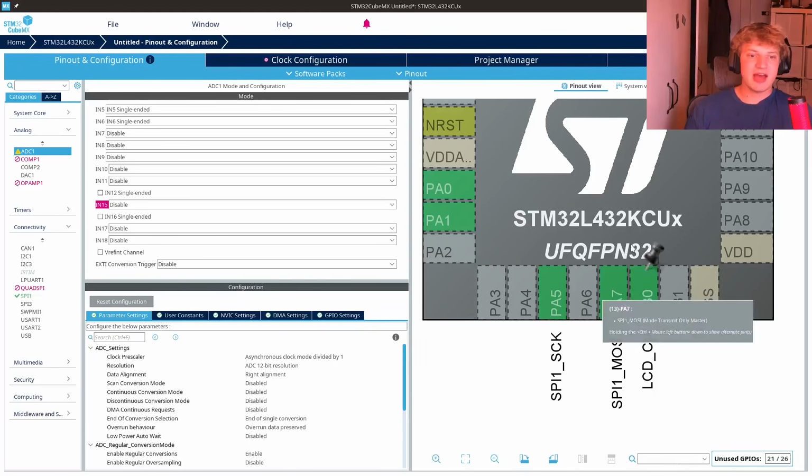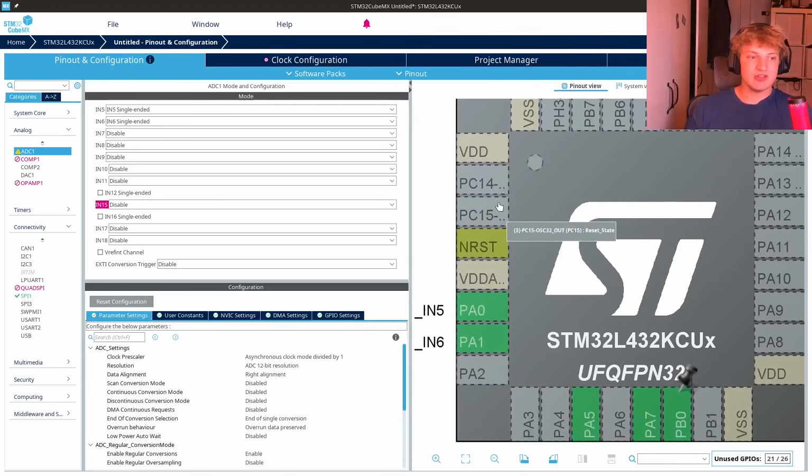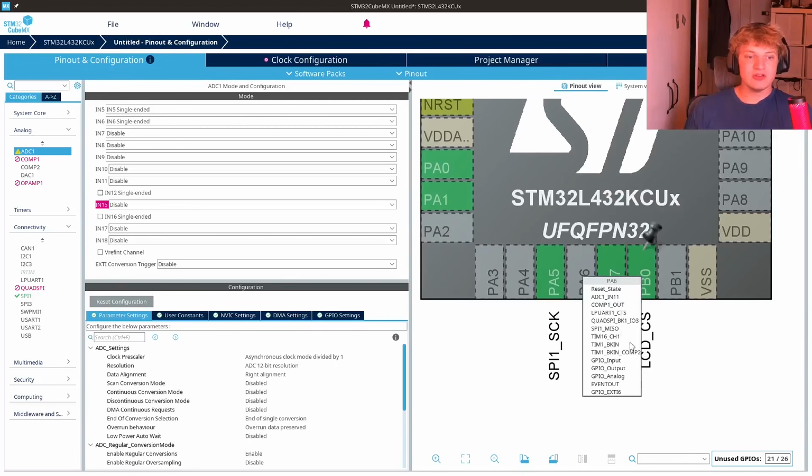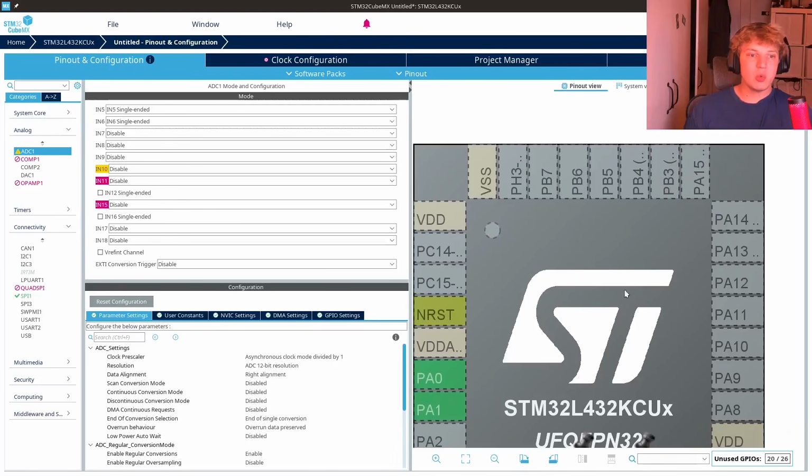If you look, we have A, we have B, and we have C. Now, if you click on this, you'll notice GPIO EXTI6 for PA6, right? So each pin, like PA6, does not actually get its own dedicated interrupt line. It shares it with similarly named pins. So for example, GPIO EXTI6 would be shared with PB6 right here.